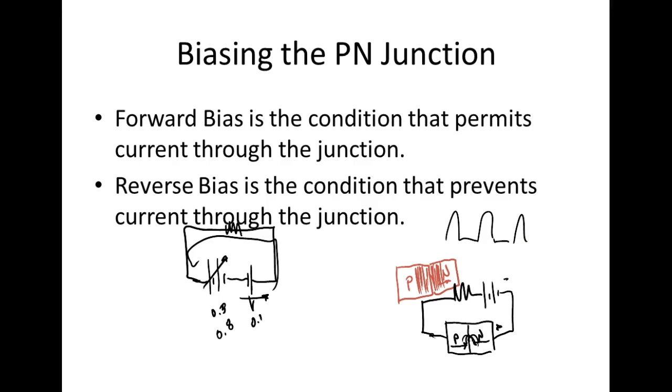We'll look later on as we get along. So understand what's happening. If I put this on a diode, and then I come over here and put this on a diode, well, when it goes positive, it would be forward bias. When it goes negative, it would be reverse bias, right? You understand? So one way it's going to let what? Current go through. The other way it's going to block it. And then we'll learn later on how we can get that other alternation up here, and then we'll start moving more toward DC. So this is one of our main uses for a diode.